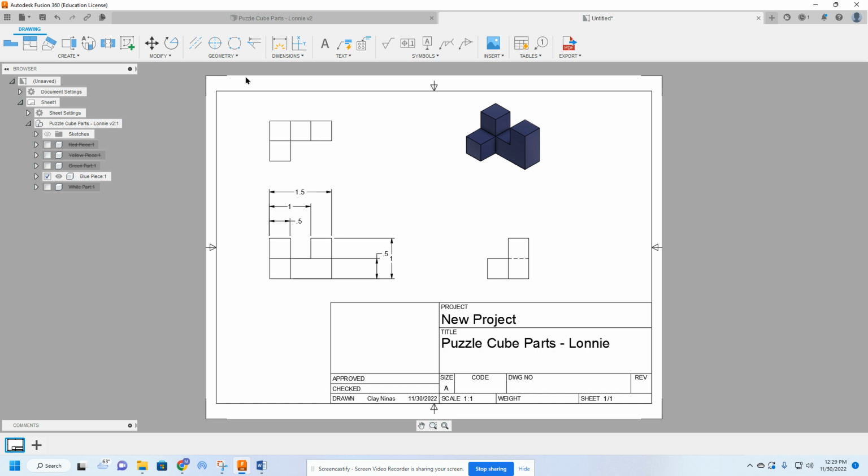Now I'll show you another way that we can manually place dimensions when we do depth. So same thing. If I'm going to place the depth out here to the right, the line is going to run vertical like this. I'll click the horizontal lines. Here, I want a dimension between here and here. Let's pull that out. And then I can just also say I want a dimension between here and here. And we just pull that dimension out. Right click, OK, and now we're fully dimensioned.